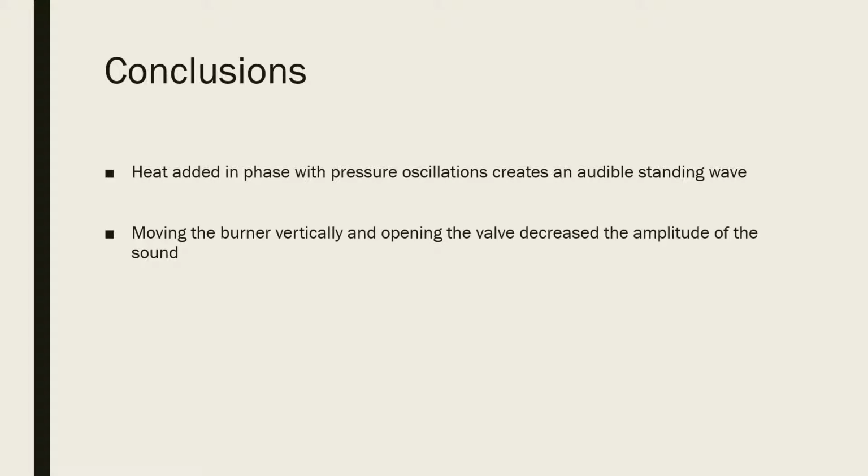The conclusions we drew from this experiment were that heat added in phase with pressure oscillations creates an audible standing wave. The reason for this is that we are adding heat in phase with the resonant frequency, which means that the amplitude of the output is greatly increased, moving it into the audible range for humans. We also determined that moving the burner vertically and opening the valve decreased the amplitude of the sound.